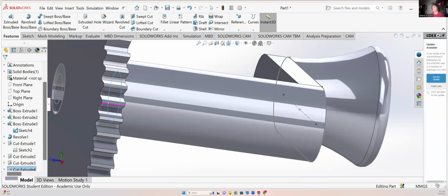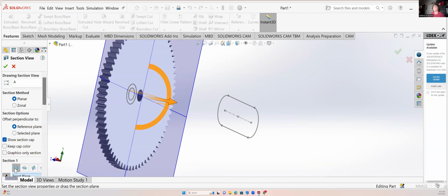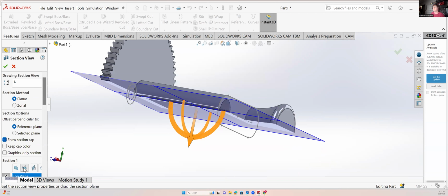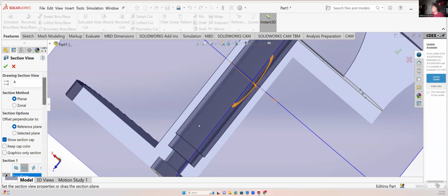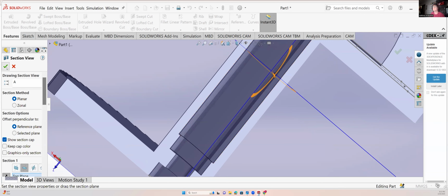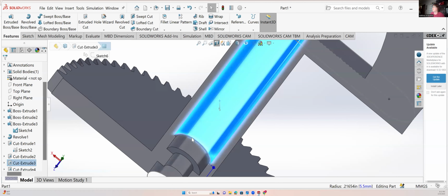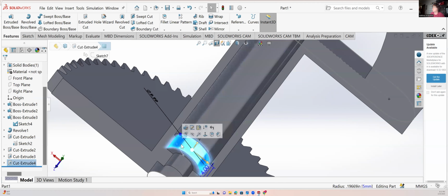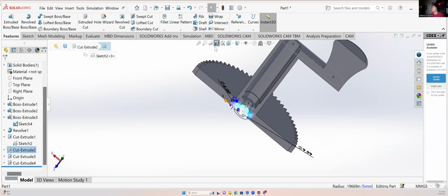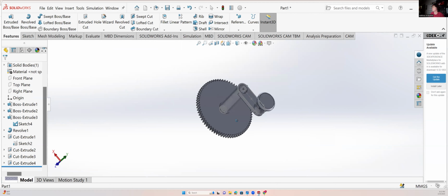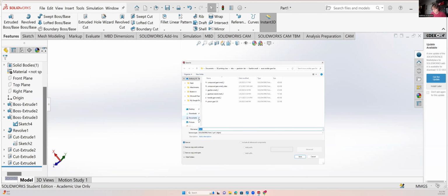And perfect. So we do a section view cut. So section, and let's do not that one. That one? Yeah. So you can see just what it's doing on the inside there. So we have that portion of the bore. Let's click check. We have that portion of the bore, which is just clearance so that we could slide our bearing down into this portion, which is so in that portion, one of the bearings will be pressed, and in that portion, the other bearing will be pressed. All right. So we'll take our section view out. And so that looks pretty good. So we're gonna name this gear crank or whatever you want to call it.